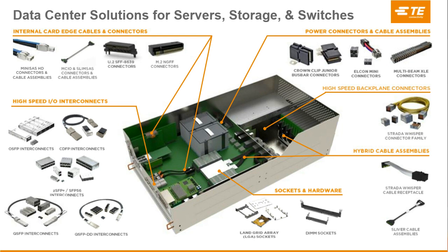The increased power dissipation, coupled with the higher density, makes thermal efficiency and thermal mitigation strategies a critical design attribute. TE brings to the table thermal solutions like its ZipperFin heatsink technology, our thermal bridge technology, and our thermal bridge heatsink technology to create reliable solutions. Because as the equipment gets hot, junction temperatures rise, reliability goes down. So TE helps drive system uptime to its maximum number.